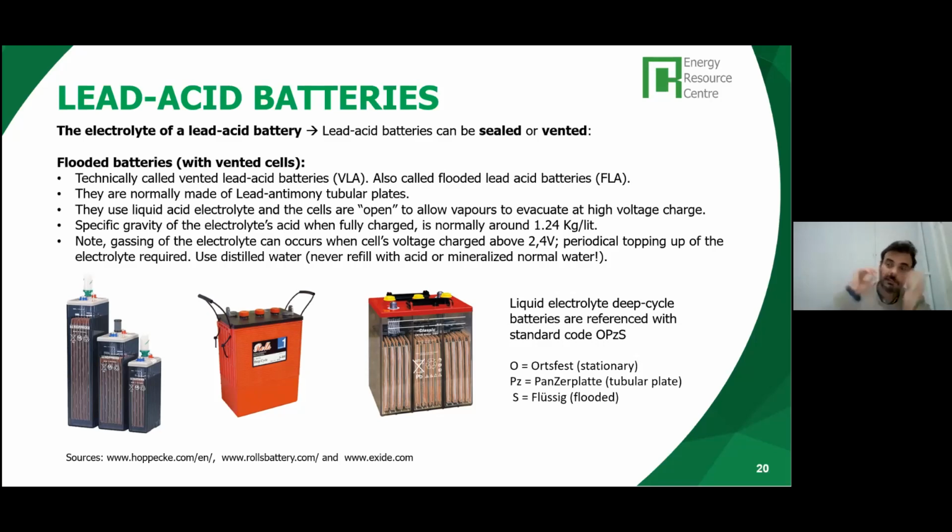I mean, they are closed with a cap, but they can be opened, and in a way they allow the vapors that generate when the batteries are charging, mostly hydrogen vapor, to evacuate when the battery reaches the high charging voltage levels. So there is a certain loss of hydrogen ions that needs to be replaced by adding water, distilled water, pure water, not mineral water, to top up the level of the electrolyte, because the acid will stay, but some of the water will have evaporated.